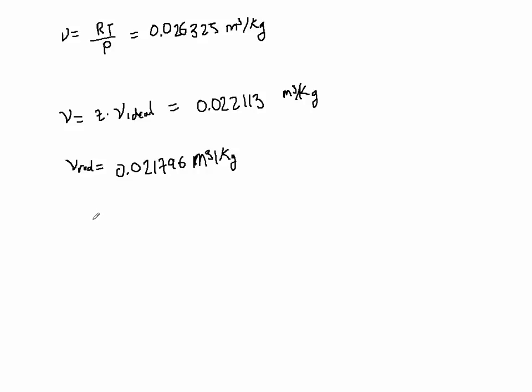Okay, now we have to calculate the percentage error to the actual value that is provided in the tables. So once again, we have the ideal value, and we got the corrected value using the compressibility. So for A, if we calculate the percentage error, which is simply the calculated minus the real divided by the real times 100, we find that for the first part, the error is equal to about 20%, and for B, the error is equal to 1.45%.